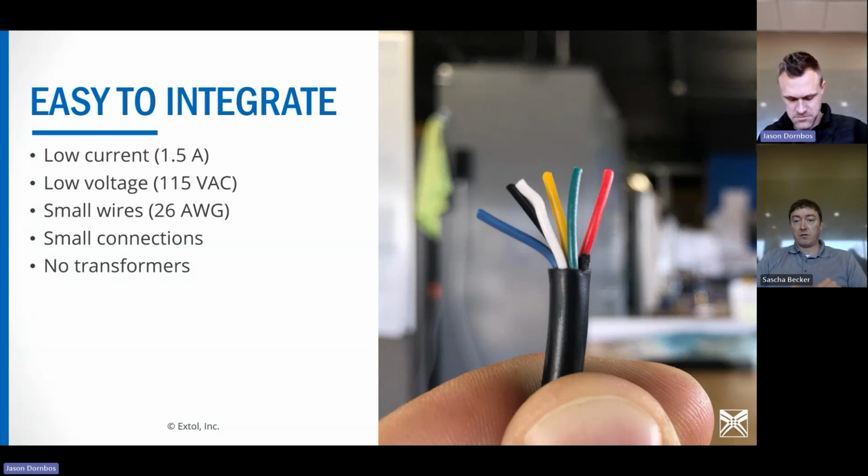Can nanoSTAKE or InfraStake work on coated surfaces? We typically don't recommend that. We ask to mask all bosses if you're doing a paint or a chroming or something like that. Especially if you have some kind of chrome surface, the InfraStake doesn't work well. It just reflects a lot of that energy. And then conversely with nanoSTAKE, you have to heat everything conductively, so that adds a little barrier to heating the resin.